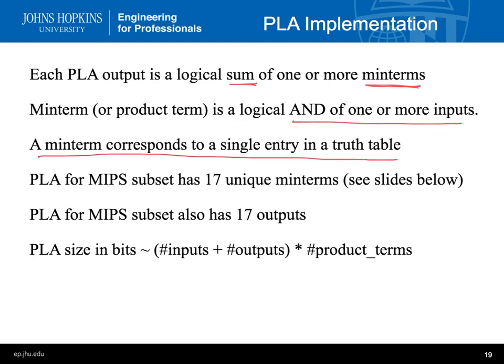You'll see what this means, but we're going to have a bunch of possible states. That would be those 10 bits. And we're going to see that rather than 1024 times 20, there's really only 17 possibilities. And so we make a PLA that's a lot smaller than 1024 times 20. Like, instead of 1024 possibilities, it's really 17. And so then we have 17 possible outputs, and so it's a lot smaller. So let's see how we implement.